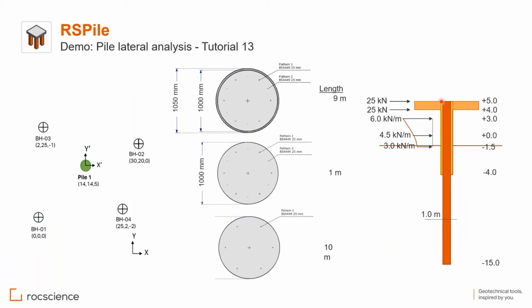I have the following conditions. I have a permanent casing at the top part. After the permanent casing, I have 1 meter continuing with the same reinforcement. Then the reinforcement is decreased to half after that one. So I have 3 parts of the pile. And I have a deck here, which is not allowing the rotation of the top part.